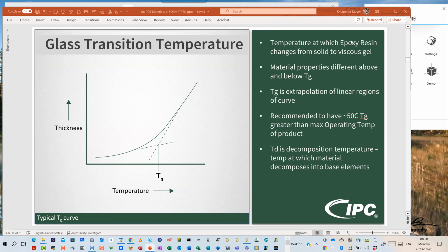Most often it's in your R's and C's, right? Your resistors, you go that high in temperature, your resistor now changes resistance value based off TCR, right? And now what was a stable corner clock frequency or filter frequency is not. Or you get a larger voltage drop across the resistor, and so on and so forth. So that's the whole point of HALT and HAST.